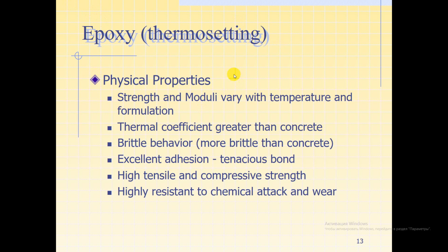Physical properties: strength and moduli vary with temperature and formulation. Thermal coefficient greater than concrete. Brittle behavior, more brittle than concrete. Excellent adhesion. Tenacious bond. High tensile and compressive strength. Highly resistant to chemical attack and wear.